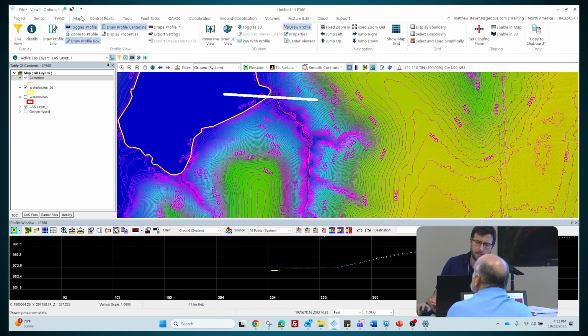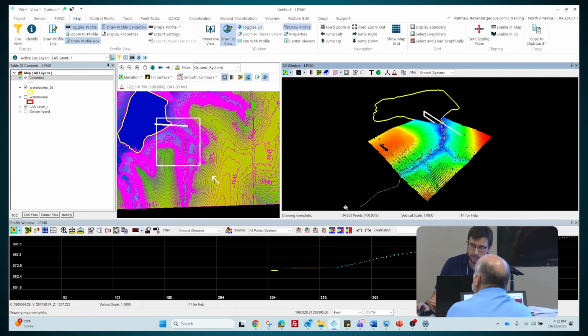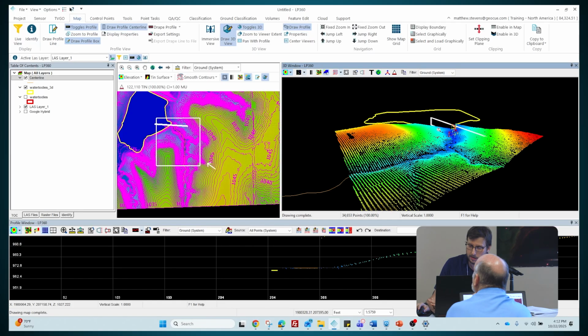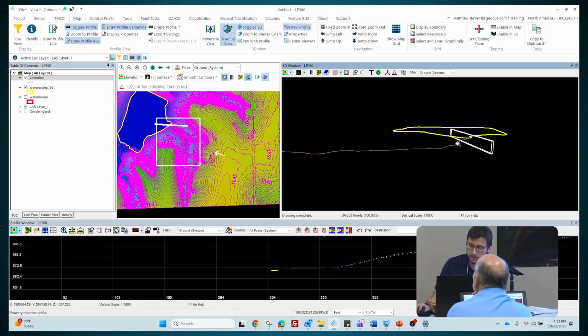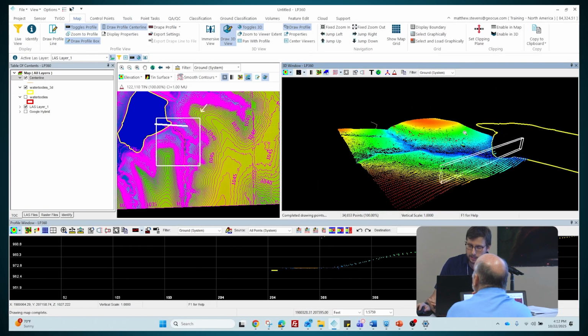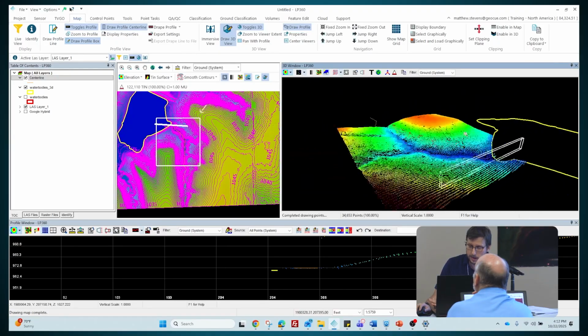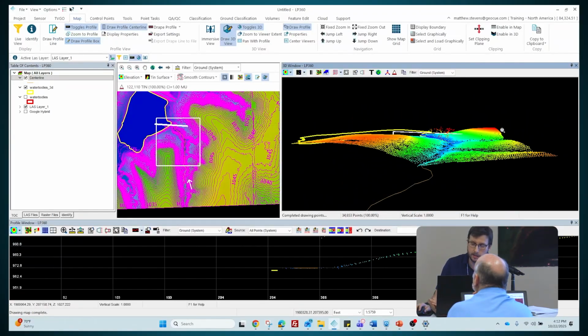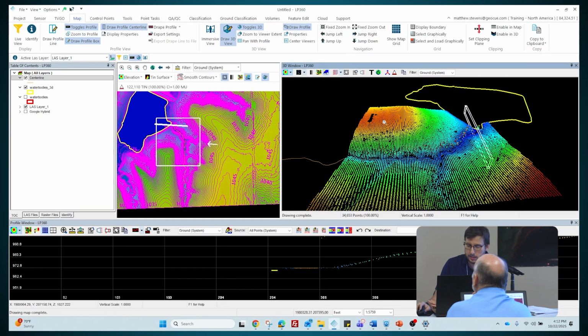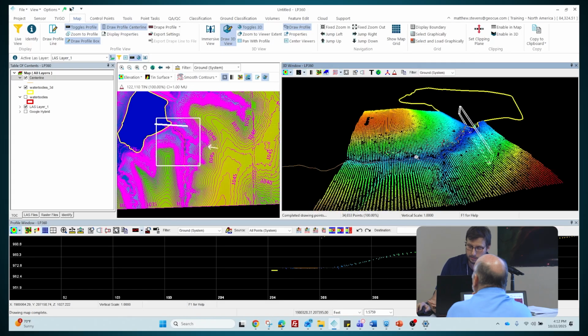Click on the map tab at the top. Click on the draw 3D view, and then just left click and hold, and let's kind of lasso that spot where we did the downstream constraint. And now I want you to toggle, this is the display legend, I want you to toggle that off, and you can see how, even though we've clicked in spots, there's lots of noise here. And if we had our conflation set a certain way, that would mess our downstream constraint all up. You can see how it's burned through that data, and it's continued to go in downstream direction.